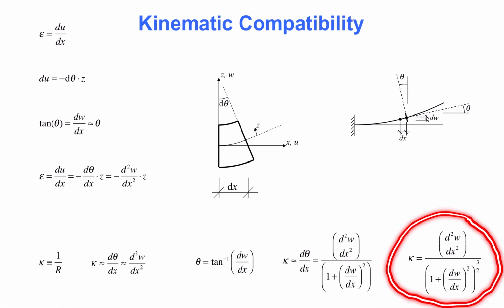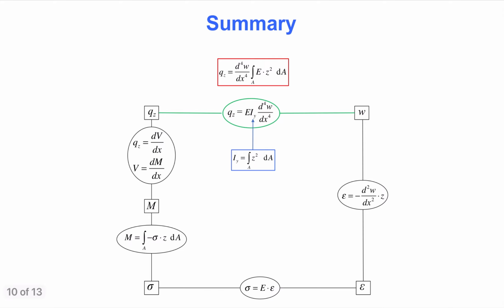The next slide provides a summary of the equations that we derived in this video. The equations are also combined into the complete differential equation for beam bending, which is marked with green in this figure. The moment of inertia has been defined, shown in the expression identified with a blue color. In the development of this differential equation, it has been assumed that the cross-section is homogeneous so that the Young's modulus, E, is constant. For composite cross-sections, this assumption is not valid.